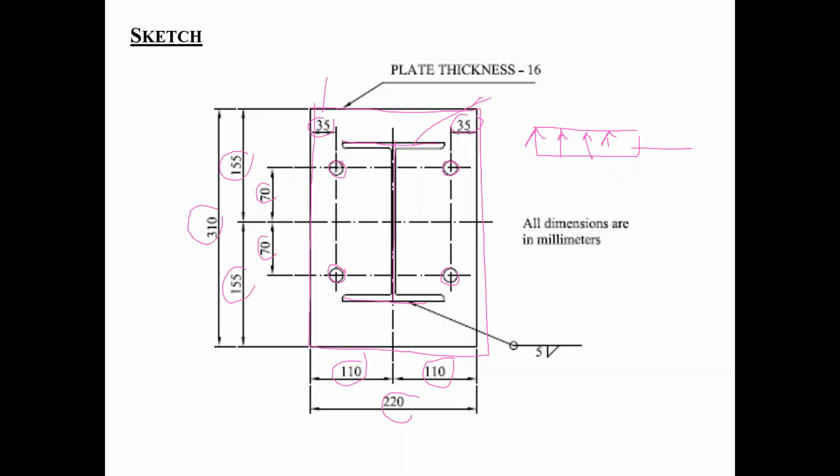And so on. Here I show 4 bolts, and this is where I'm telling you, because of that one worker that got killed because the column collapsed on him while he was climbing up the column while erecting the steel. The standard requires a minimum of 4 bolts per column, and this is not because you need it, quote unquote, for your structure. It's more for during erection, to minimize the risk that somebody else is going to get killed.